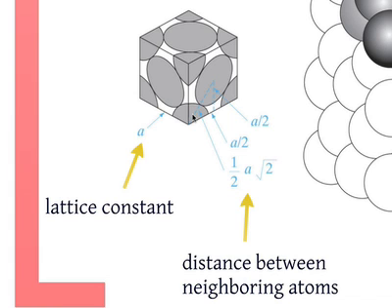That number is the closest packing that you can get of atoms. Now, why is this important? Because that determines the atomic density, how many atoms can actually fit in a particular crystal. Now, you can see one very important concept here: the atomic density is different with direction. If you look in this direction, they're very closely packed, whereas if you look in this direction, they're not so closely packed. What does that mean? That means that the properties of the material can change with direction. This will become important later on. It's stronger in one direction than the other.